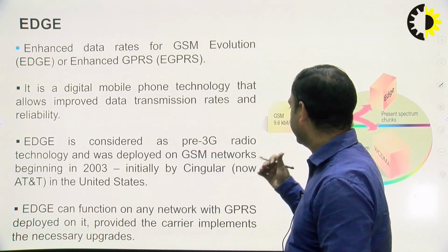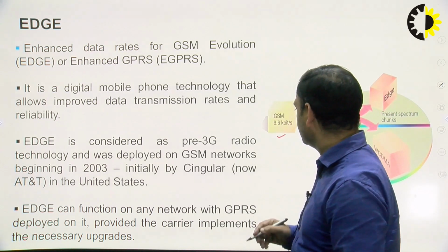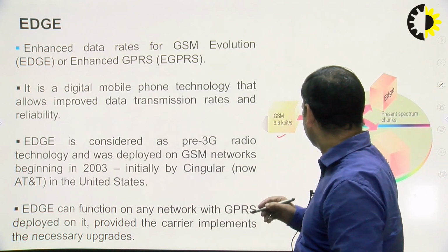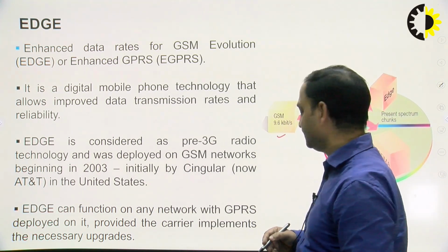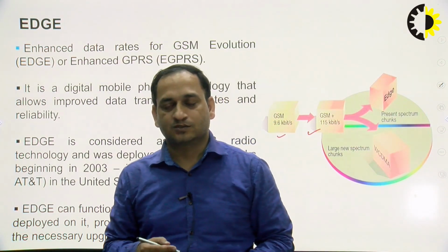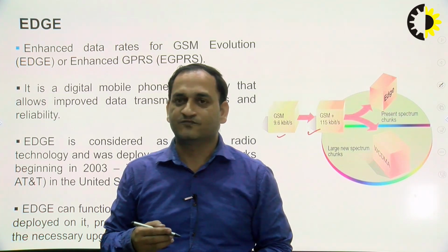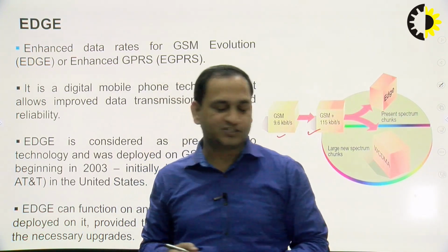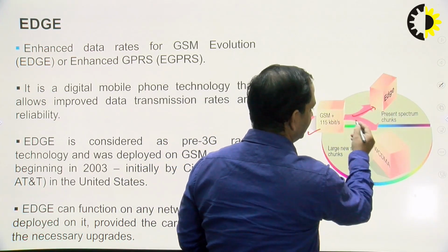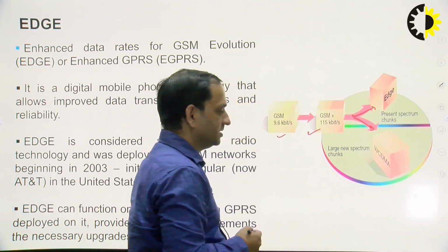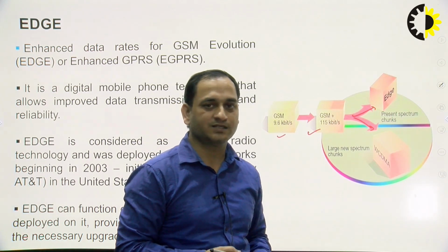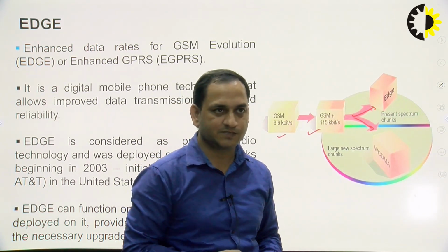Here we see that the GSM network used a 9.6 kbps data rate, and then GPRS used 115 kbps. So there is an enhancement in the data rate, to get up to the 2.75G network, that is the EDGE network. It is bifurcated into two ways: first is EDGE, and then WCDMA. This bifurcation, or these technologies, were proposed by the 3GPP, the Third Generation Partnership Project.